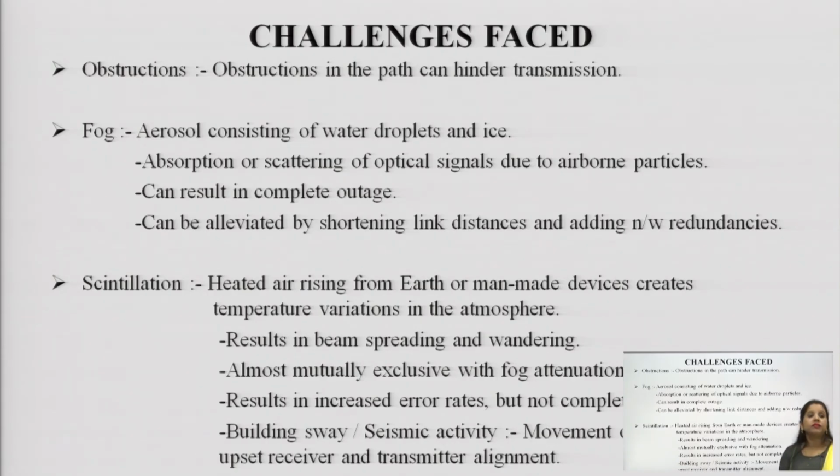Already when we have studied noises or the absorption process, any water droplets or ice present in the fog will either absorb the signal or lead to scattering of the signal. It can result in incomplete outreach, and can be alleviated by shortening link distance and adding network redundancy. So these are the effects which arise in free space optics due to the presence of fog.